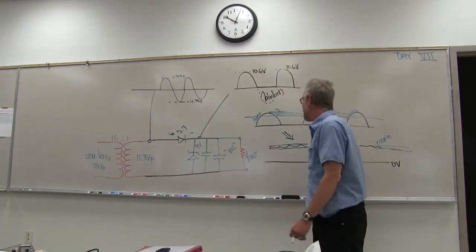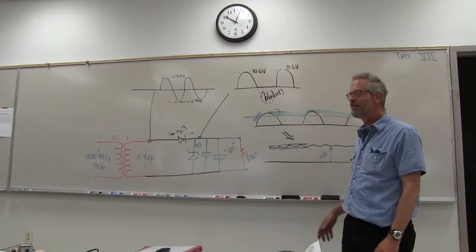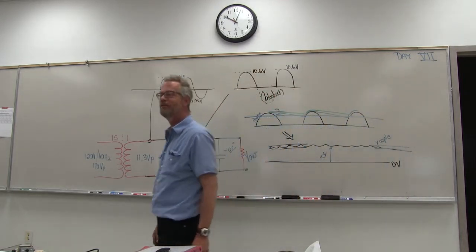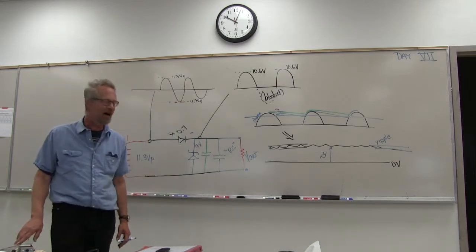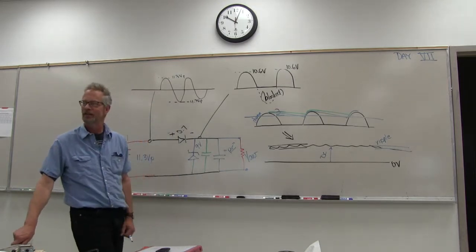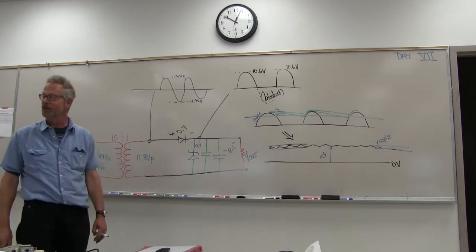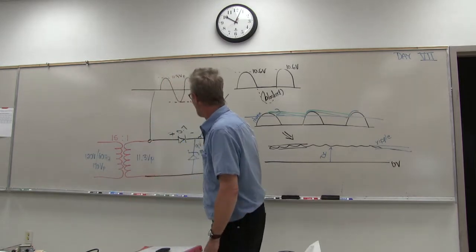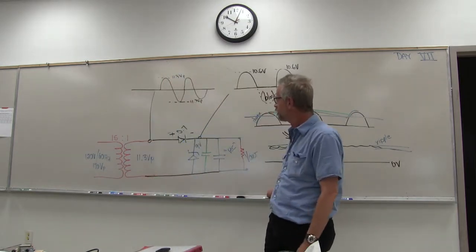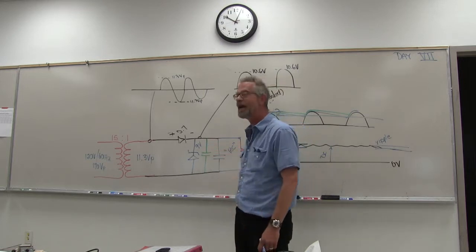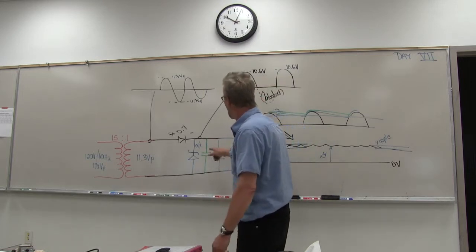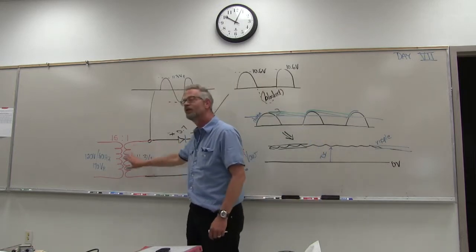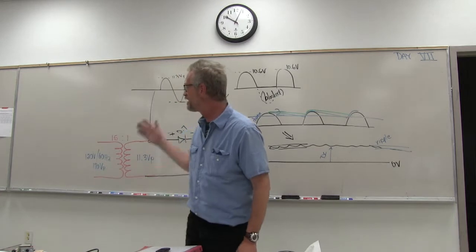We'll see that a little bit later because we did draw up a block diagram, but there are other more complex block diagrams for a power supply. This is just the very basic, simplest possible power supply that we can come up with: a single diode as a rectifier, a single capacitor or group of capacitors, and remember, if we have 2 capacitors, we simply add them together to get the total, as a filter, and a simple transformer to get our voltage into the ballpark.